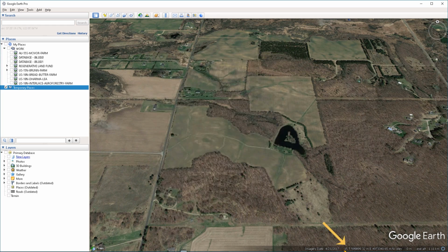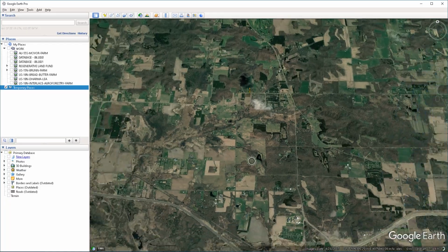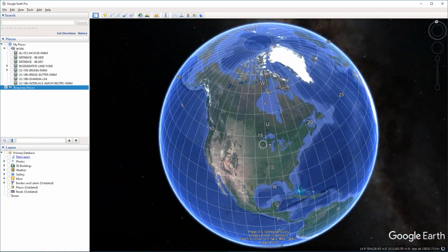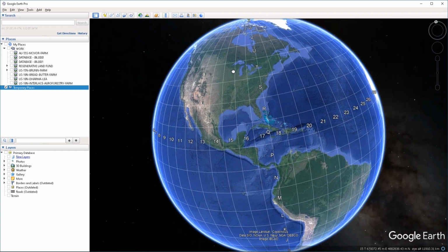And in the bottom right corner, we're going to find a number and then next to the number, a letter. The number is the number of the UTM zone and the letter you can disregard completely. So all you have to know is which hemisphere you're in. Is it a Northern Hemisphere or a Southern Hemisphere? So if you're in the Northern Hemisphere, then the letter is N, and in the Southern Hemisphere, it will be S. Now, I know this is in the Northern Hemisphere, and just to confirm that, I can zoom out a bit. And we can see that this is well into the Northern Hemisphere.